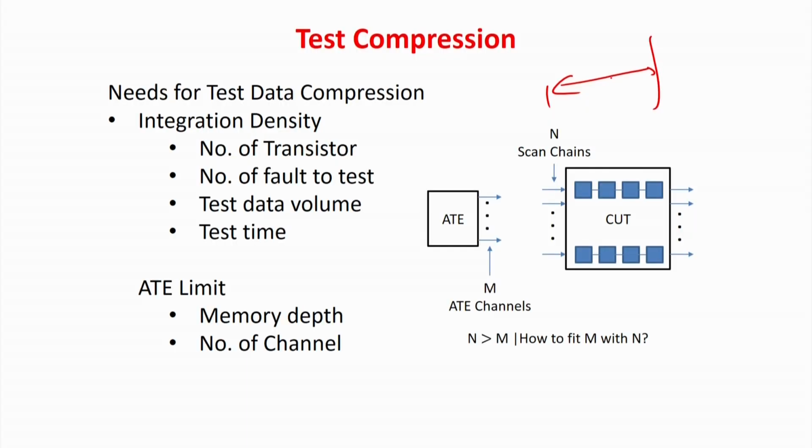Say for example, I have 100 faults. An ATPG algorithm will give you some 20 patterns or 10 patterns which will be able to cover all the faults, and there are algorithms which will give you the minimal number of patterns to do that. If you further reduce it, you may lose on coverage. So compaction in this manner, reducing the number of test patterns, is a different problem than test compression, which we are trying to do today. Reducing the number of test patterns means you have to find the minimal set which can cover all the faults modeled. That comes under automatic test pattern generation and is a well studied area.